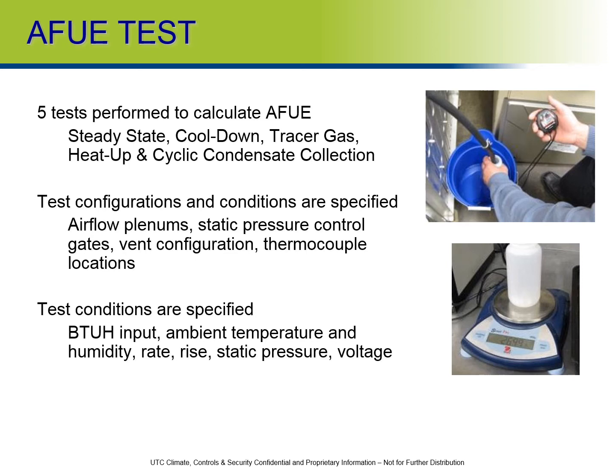And then the other thing is thermocouple locations. When you're taking temperature readings, are you taking the temperature reading directly above the equipment in the plenum? Are you taking your temperature reading up and around the corner in the trunk line, or if there are multiple trunk lines, are you taking your temperature readings in each trunk line and then averaging them? Because this all directly impacts the performance of the furnace or fuel burning equipment.